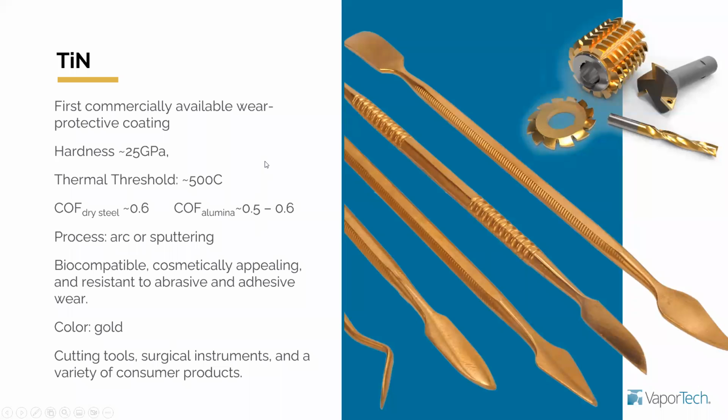Changing materials now. We're all talking about just PVD so far, right? With PVD, you have a metallic source, a solid source from which you create your coating in combination with different gases. So titanium nitride is probably the most common, maybe. Nowadays, it's difficult to say, but it's the oldest performance coating and decorative coating that has been used since the 70s.